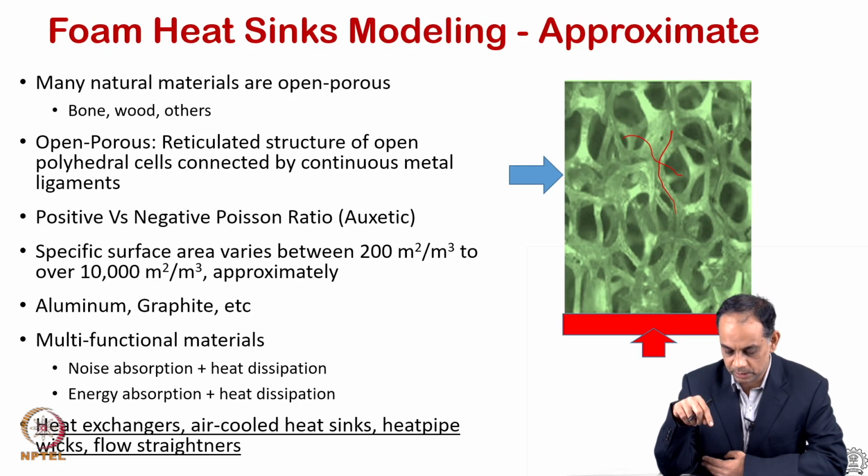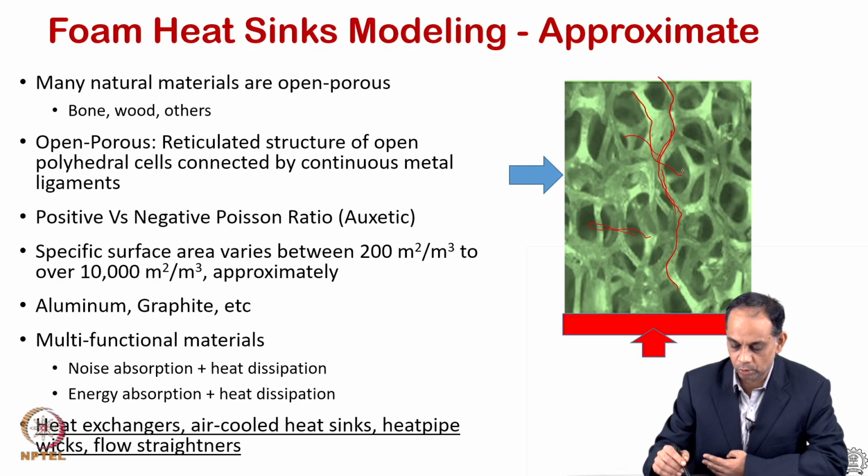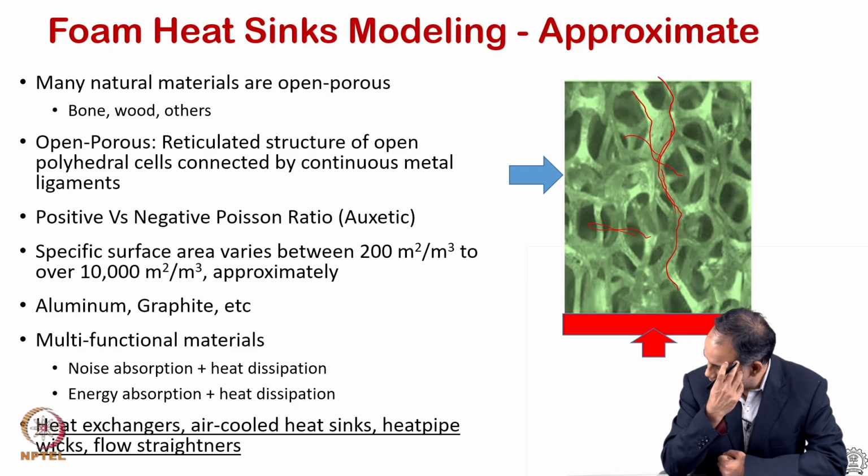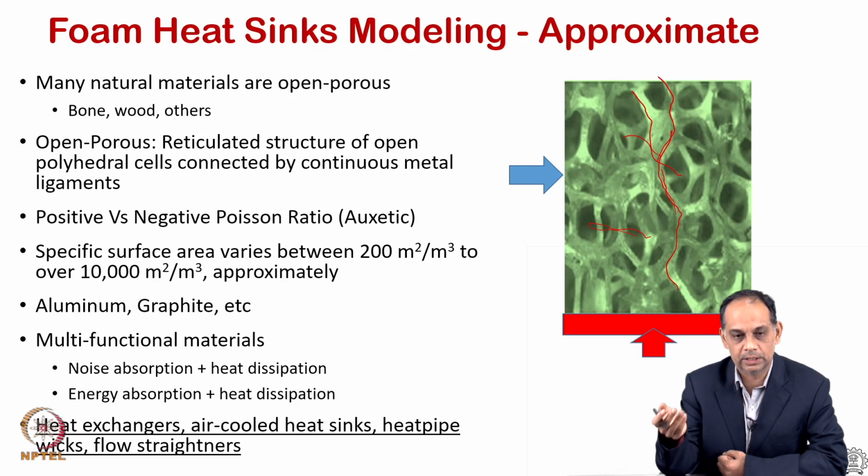Here in porous heat sinks, the porous metal heat sinks, the flow paths are interacting. The pores are interconnected, and the metal path is also continuous. So heat will flow simultaneously, and the flow will also go through these porous areas and pick up heat from the metal wall. There are many varieties of metals being foamed, all the way from aluminum to stainless steel or